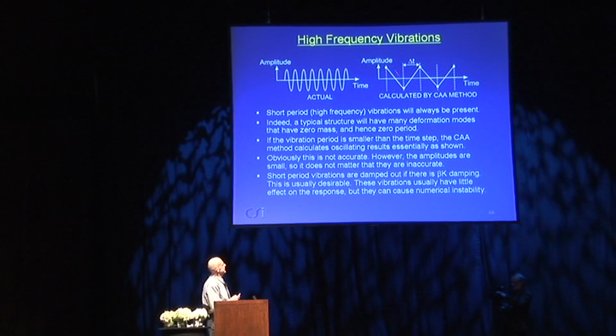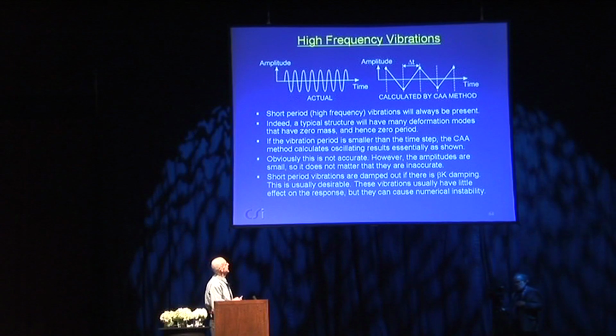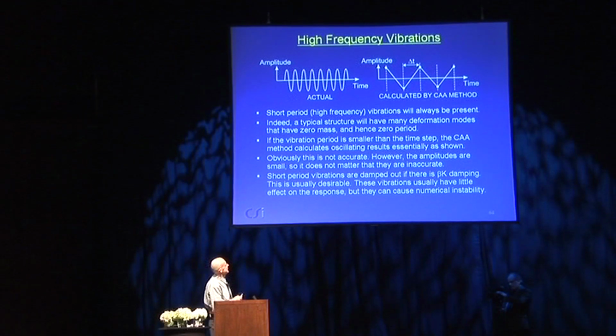The method still works. It'll still calculate a result, but it'll just calculate an oscillating set of results like this. And usually with a controlled amplitude, the amplitude is often not too different than the proper one, but clearly this is not a very good approximation to this. So if the time step is long compared with the period of vibration of the structure, you're not going to get an accurate result. And in any particular mode, to get a reasonably accurate result, you need a time step of no more than 1/10 of the modal period.